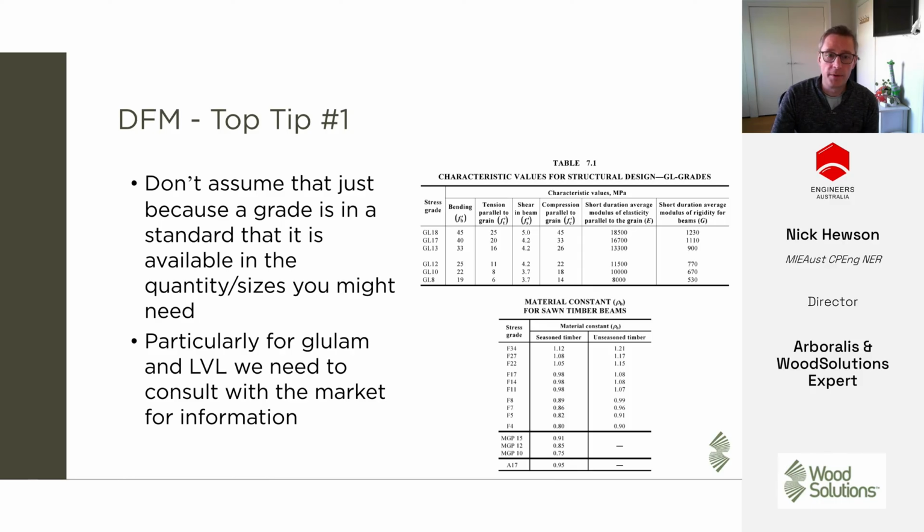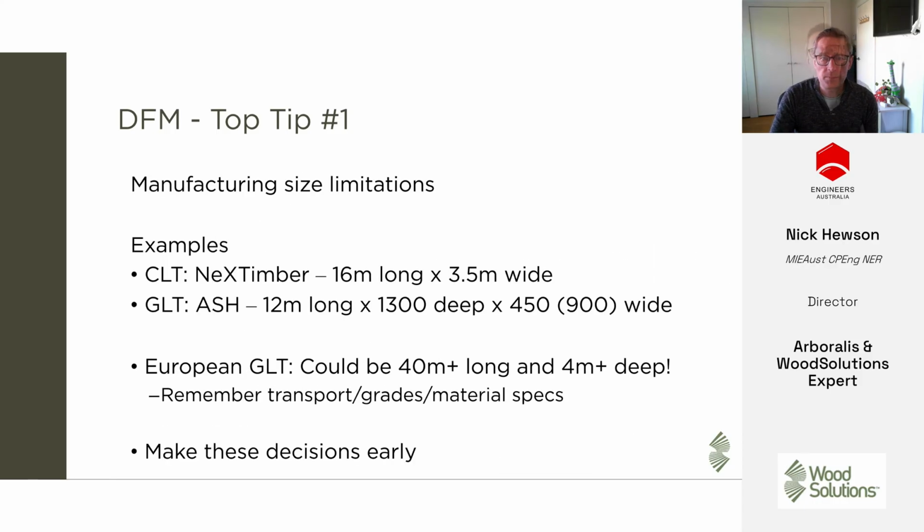I've had a number of projects I've seen where people have kind of designed in the highest grade, only to find that it's not available in the sizes or the quantity that they need, or it's too expensive, at which point you've kind of locked in depths and spans and things, and you have to work very hard to try to kind of unengineer that. So that engagement with the market to make sure that we're specifying the right things is absolutely crucial.